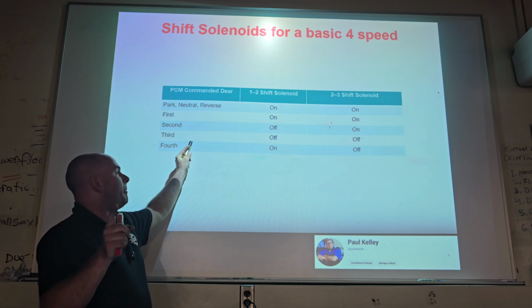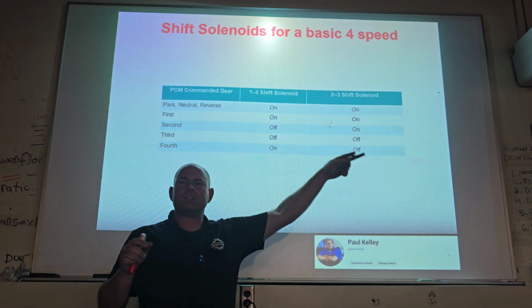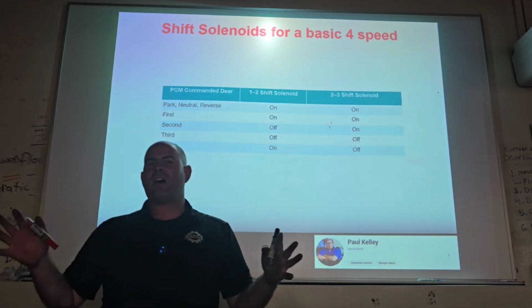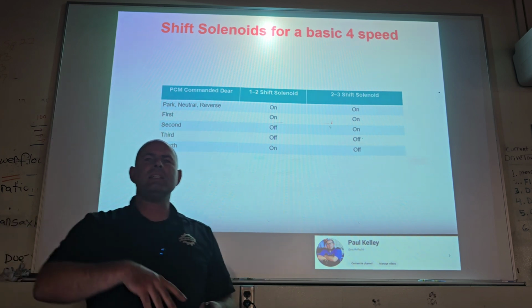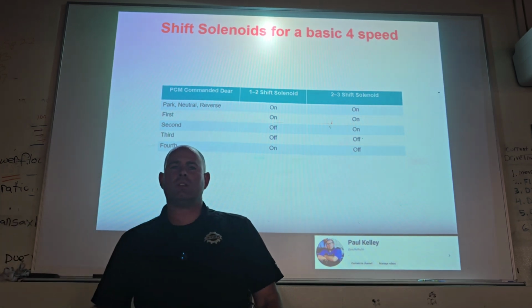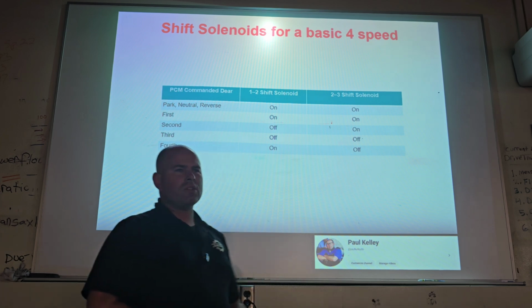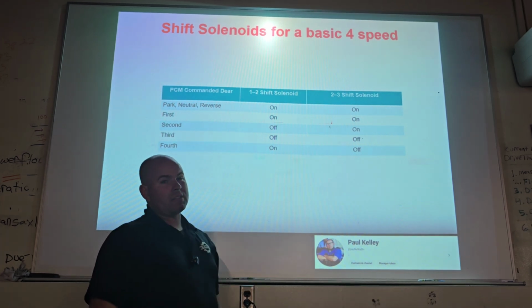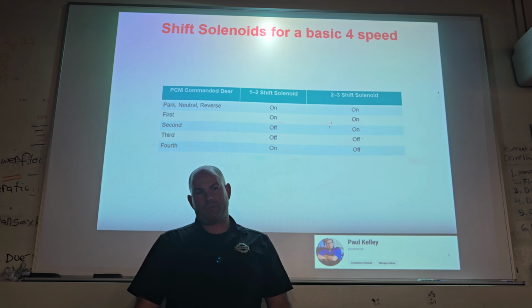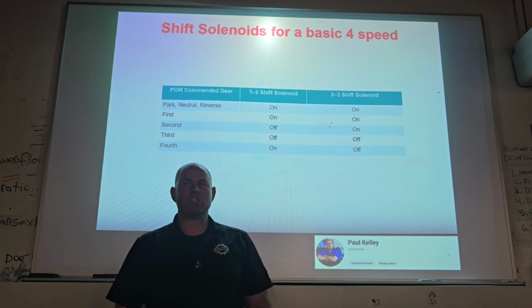Not exactly. But whatever off is what happens if there's an electrical failure. Make sense? If you have a bad TCM, if you disconnect the transmission, it'll default to whatever off is. So the engineers designed it like third gear, honestly, it's going to be slow from a start. But could you make it home on the freeway? It wouldn't be very nice though, but you could make it.